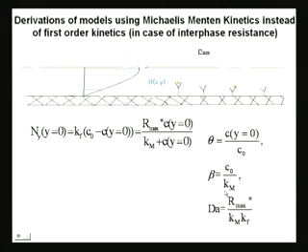Beta is a new dimensionless variable that you define, which is C naught over k m. Damkohler number over here, and you have to be careful with this, is defined with R max double prime. The double prime here signifies this is a surface reaction. It has nothing to do with derivatives.